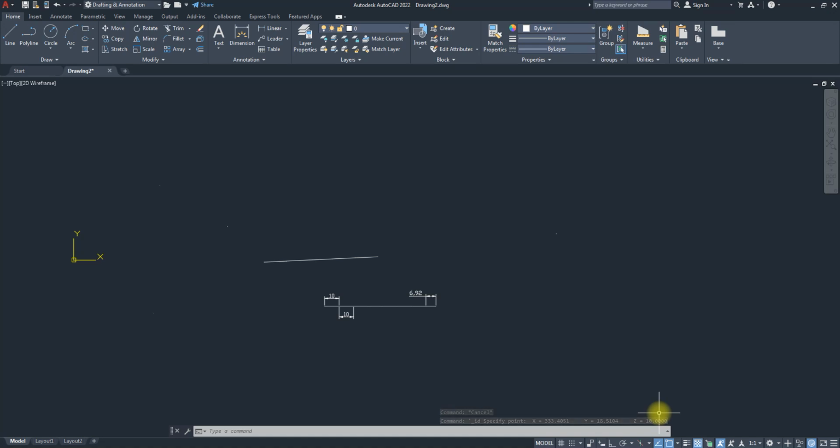So now what I've done is, before drawing anything, I've changed the height from zero, from the ground floor, to a particular height. Whatever I create now will be floating at that height. Those earlier ones will be on the ground because the elevation was zero before creating them. Do you understand? Anything I create from now on will be at that height.